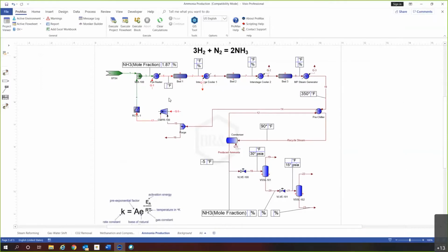So we've talked about the inlet. We can go ahead and move on to the temperature specifications. As mentioned, we're going to want to target an outlet temperature of 910. This is saying that we have a temperature controller on the outlet of the reactor, and we're supplying as much cooling as needed to produce that temperature, again, because this is an exothermic reaction.